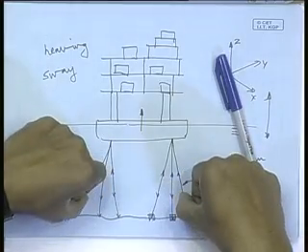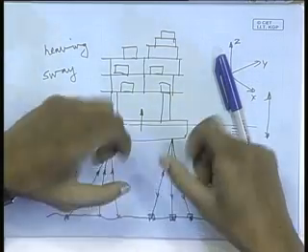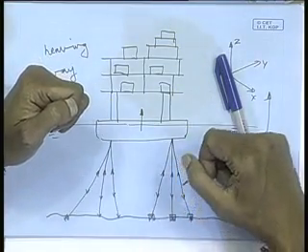So, if there is a heaving motion, then what happens? I have a drill bit, so it goes on like this, and you have difficulty in doing the drilling operation. Whereas, when you have a very long length, then if it moves like this little bit, it can withstand that. But if it goes up and down, then it becomes a problem. So, to minimize the heaving motion, these tendons or these ropes or these legs, flexible legs, are kept under tension, right. That is the concept.